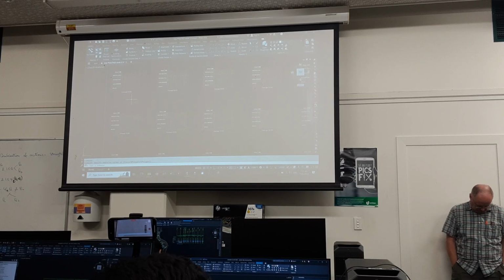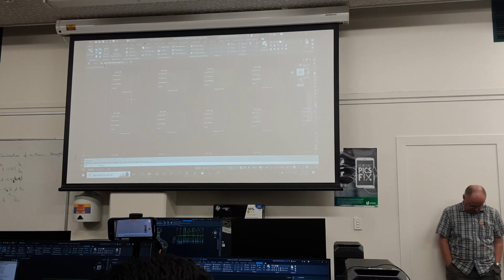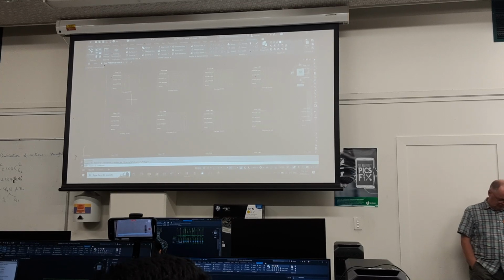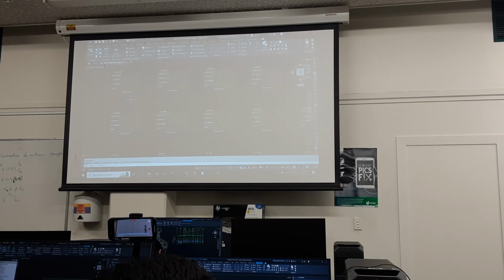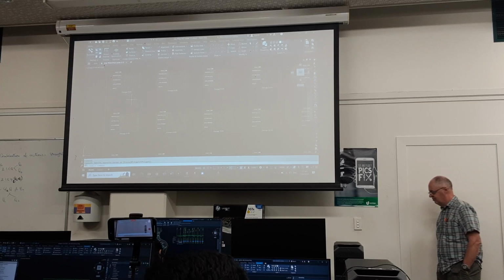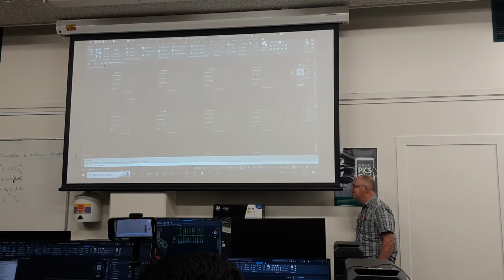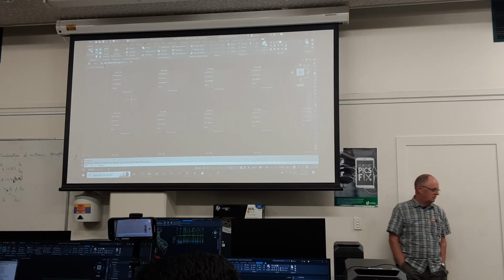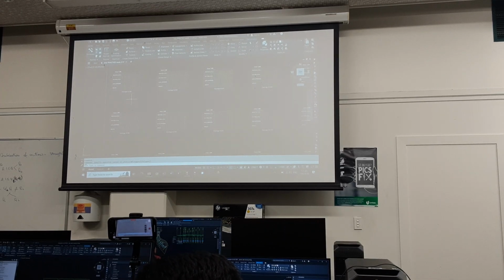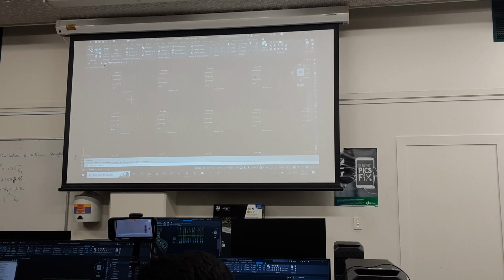What we've got left to do tonight, which is not much, is we need to export this into AutoCAD, and I'd like to show you the flatten command as well in AutoCAD. And remember, you can do this multiple times. So if you wanted to go back and just do the point numbers instead of levels, and then bring it into AutoCAD, that would mean that you would be able to join the points up in AutoCAD rather than in Civil 3D. In Civil 3D, it basically is AutoCAD anyway.